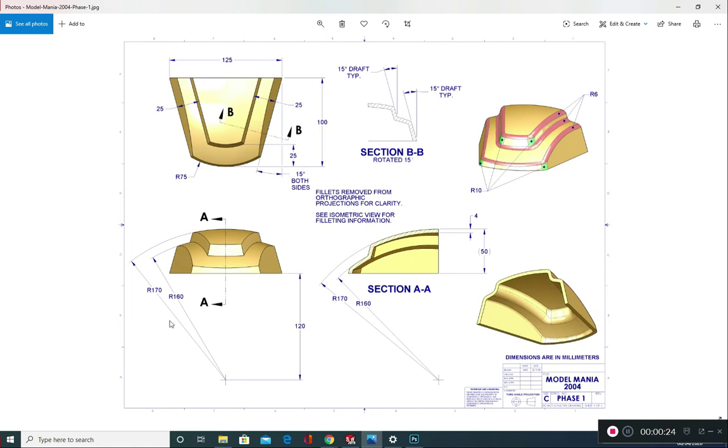It's a 10mm difference, so I could do the arc at 170, 120 from the centre point, and choose to do a revolve cut after doing a boss extrude, or I could do it a different way, which would be a boss extrude and then offset from a surface, or I could do it another way, which is one of the ways I'm going to show you, which is through hybrid modelling using surfaces. So let me just show you the quick way of doing it.